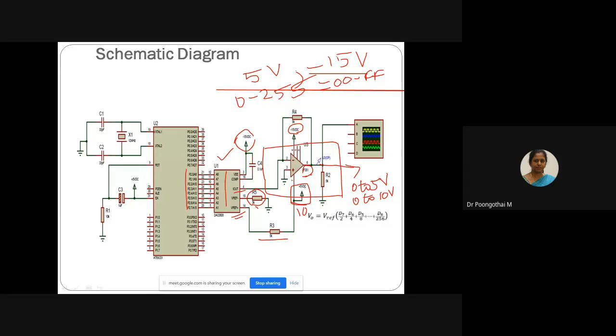So first you connect negative 15 voltage to VEE and also negative 15 voltage to the fourth pin of the LF351 amplifier. And at I out, you have to construct this I to V converter. You connect the second pin of your operational amplifier to I out and ground the third pin. And this will be your feedback resistance.